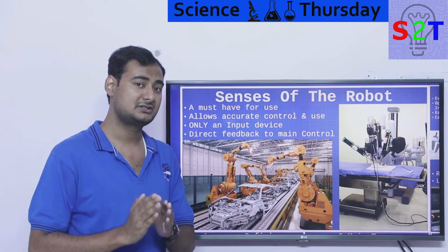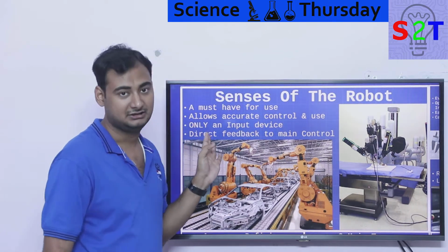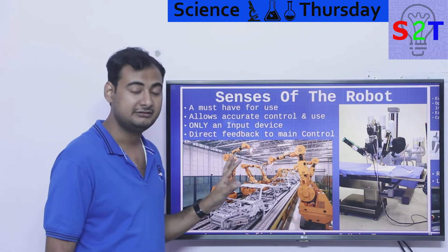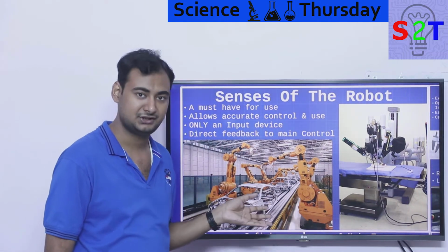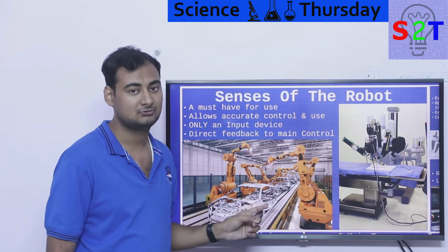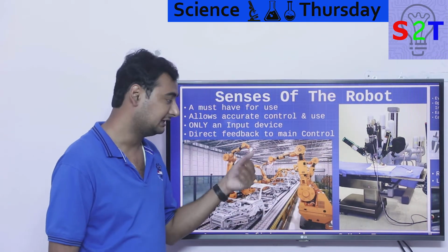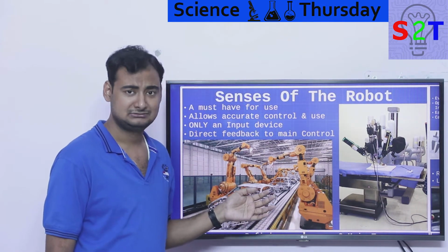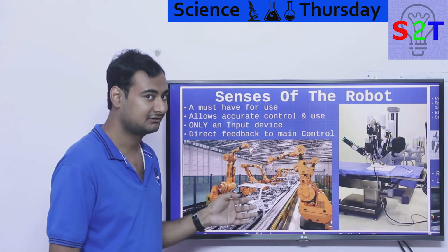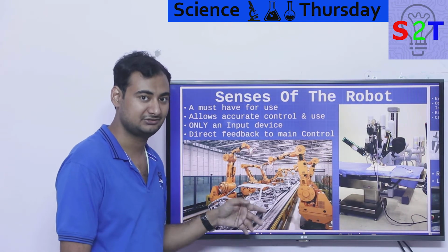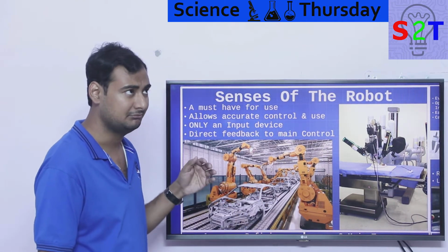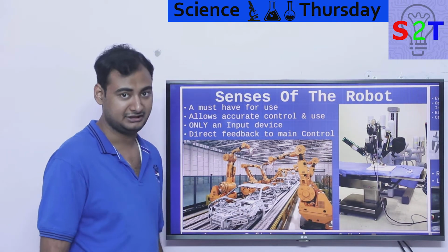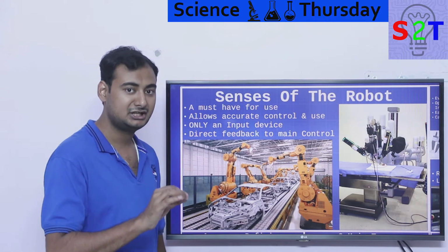The control system always takes priority when it receives a signal from the encoder. So encoder data is absolute priority. If you have any quality robot that is used for industrial use, if the encoder fails, the whole robot will be shut down. They will never risk it. It's like, hey, can I run it without encoders? In principle, should you do that? Hell no. And all your insurance will be destroyed if they ever find out that you have a faulty encoder running your robots. First of all, you may not even be able to run it. For this reason, it is quite important, and encoder data must get absolute priority.